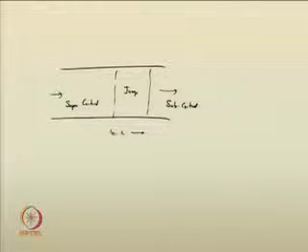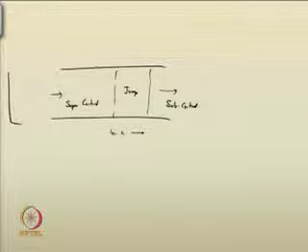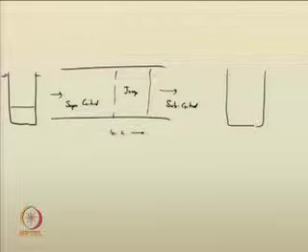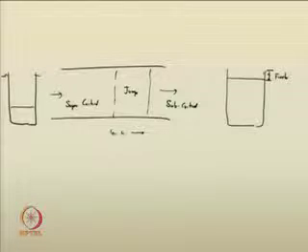So, when you design the channel, say if the channel cross section had the depth of flow like this, here, the depth of flow as this particular quantity. So, based on the depth of jump that is being considered, you have to associate the freeboard in the design. This particular length is called freeboard.